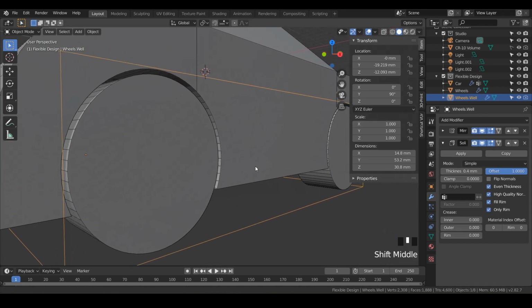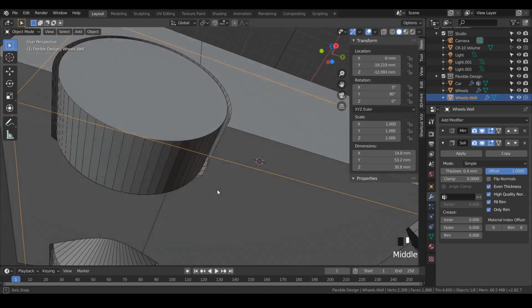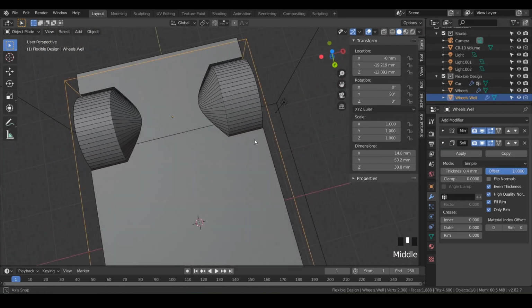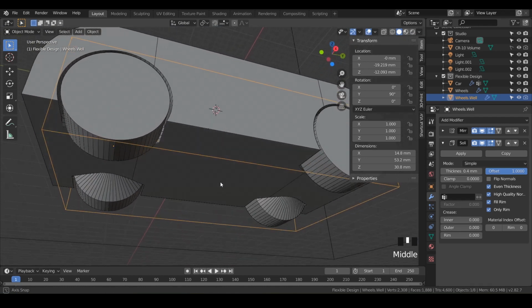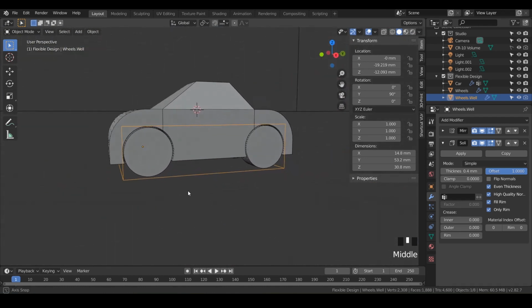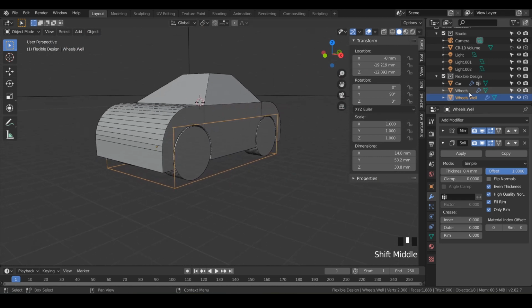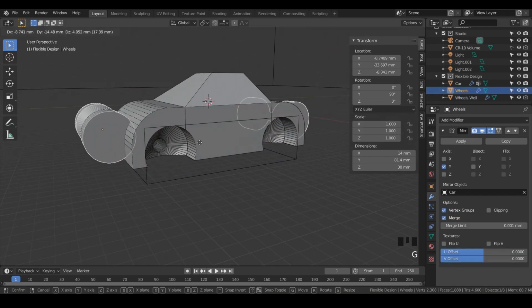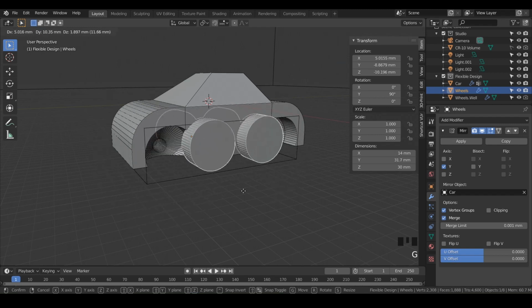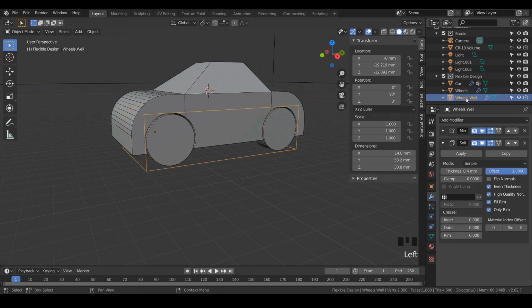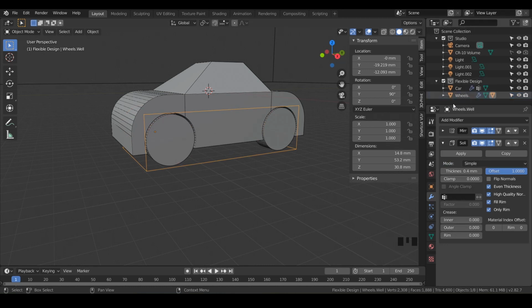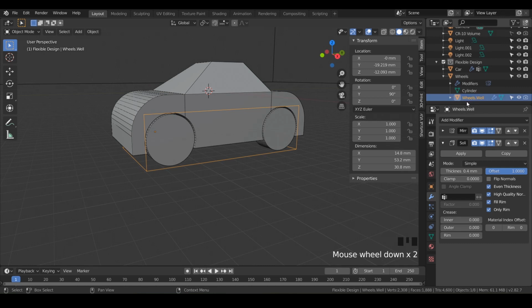And there we go. Now we've got some wheel wells, super easy, that are cut out, and that's going to let our wheels roll really nicely once we 3D print them. Everything's looking pretty good, but what we need to do is parent all these together, because if we drag the wheels and move them around, the wheel wells aren't moving with it. So let's fix that. Just take your wheel well and click on that, and then click and drag and hold that over your wheels. Hold Shift and then drop to set parent. Bloop. And now it's inside of the wheel well there.